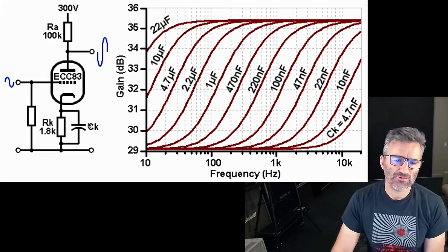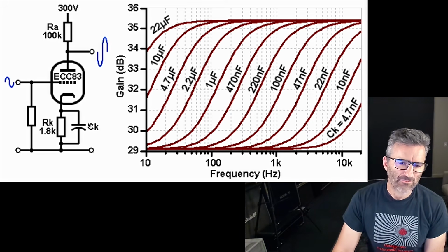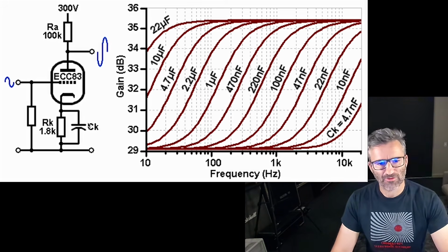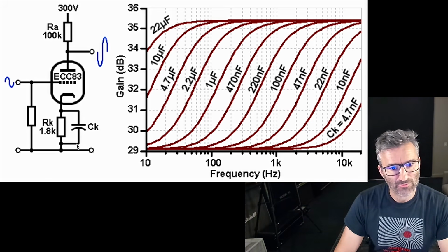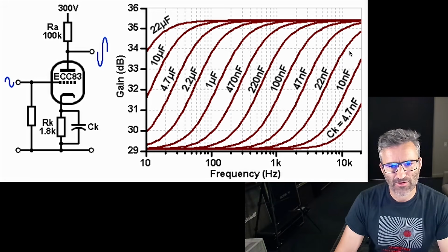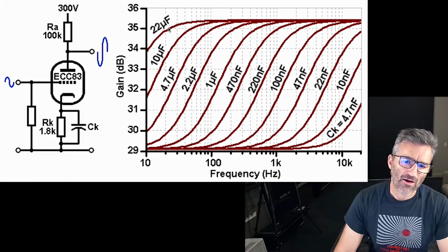It's a way of tuning the amp, a way of tuning the preamp, because the higher this capacitor, the more low end frequencies will be bypassed. And you can see this graph here on the right, which is the amount of gain against frequency, that the higher the value of this bypass cap here, the more of the low frequencies are allowed through, and you just get max gain.